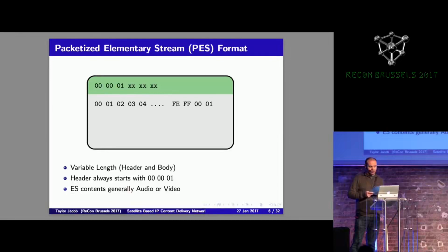Now, DVB multi-protocol encapsulation is a standard that pertains to this presentation. It defines the means to carry IP traffic over the transport stream. The key parts are one or more PIDs can carry DVB MPE traffic, and all the PIDs will operate independently of each other. Each PID's DVB MPE stream may contain more than one destination IP. The intention is to take the IP packets from one PID and put them on an Ethernet network somewhere once they're decoded.